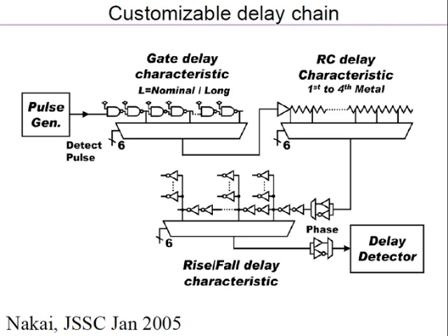So that is also an important problem. One way of inferring is this: when you test the chip at a particular voltage, you put a voltage and you run your test. You see everything is okay. Then you increase the frequency, run it again. Increase the frequency till you reach a point where it fails. Then you know for that voltage, that is the frequency at which it runs.